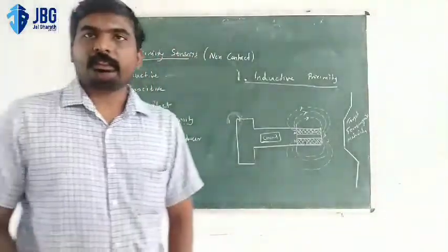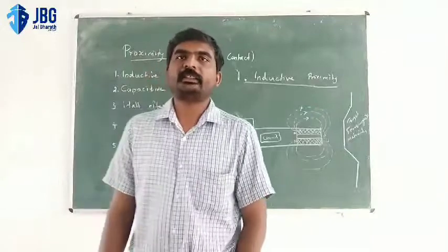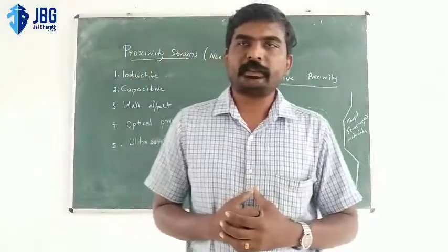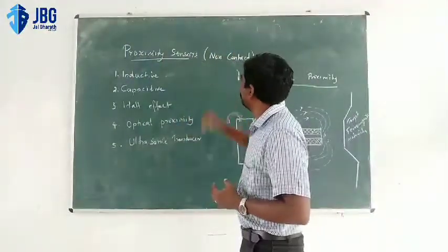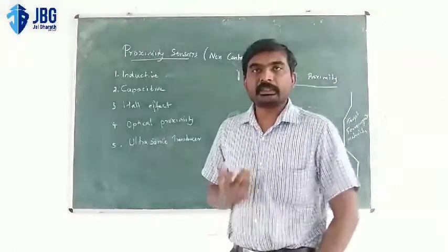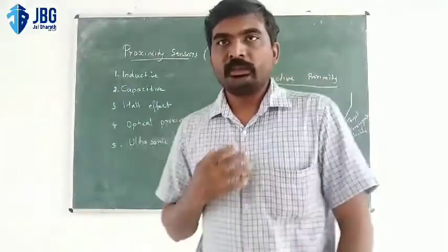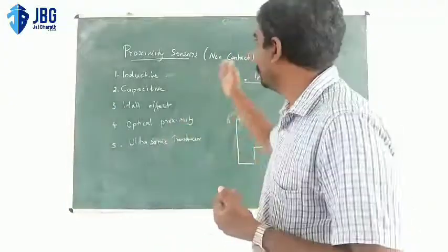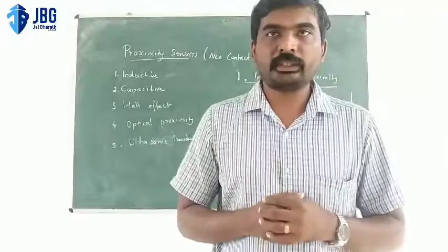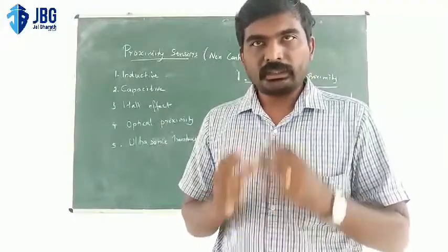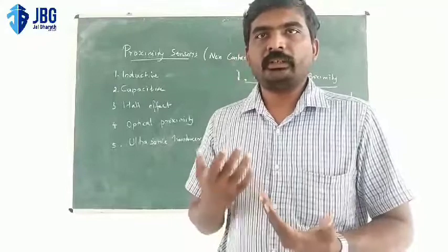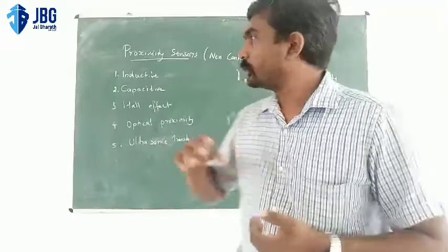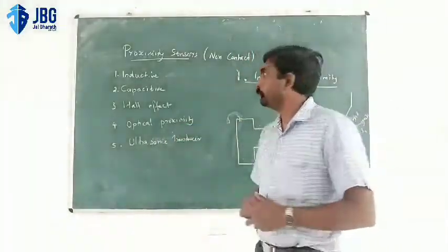Today we are going to discuss proximity sensors. Proximity sensors come under non-contact type sensors. To detect the presence and absence of an object, they do not require any physical contact with the object. That's why we call them non-contact type sensors.